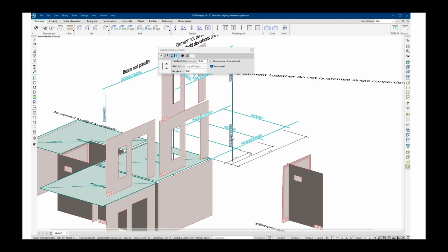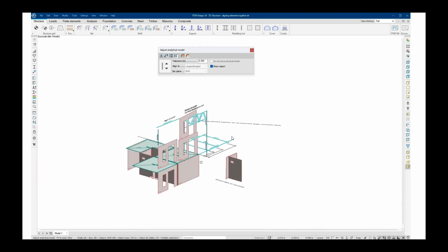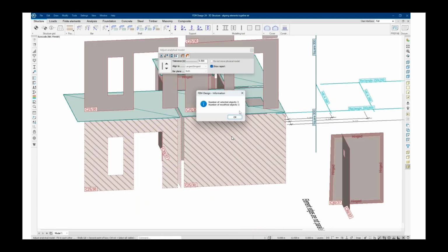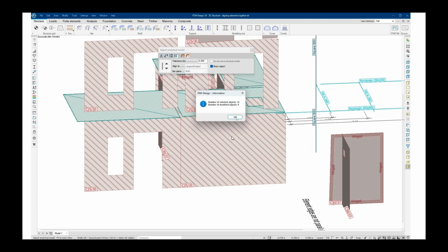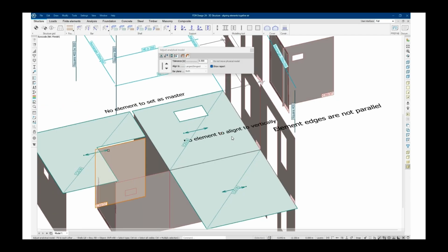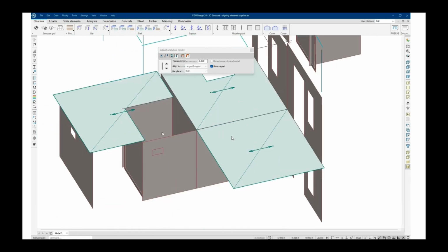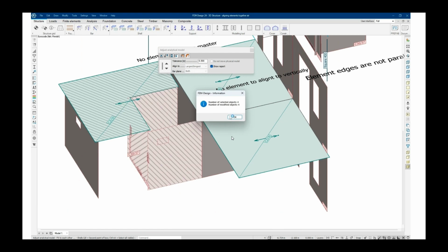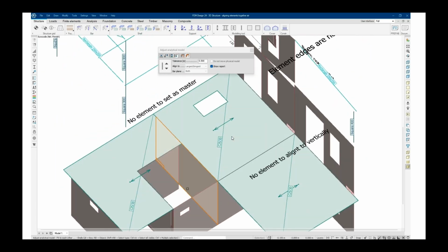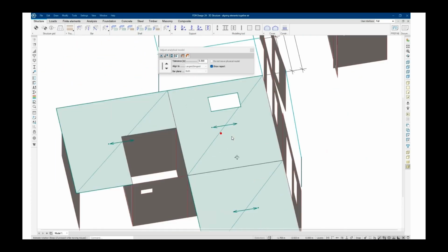Then we can just connect those elements, so we can connect shell models together. So this is the tolerance, and we can basically select any set of elements, but you should be very considerate of what you select, because it affects the result. If you select too many, it doesn't know what to do. So it's usually a better strategy to select a small set of items where you align those elements together. And this is final. Okay, we select the wall and plate, and then the wall and the plate will be connected.